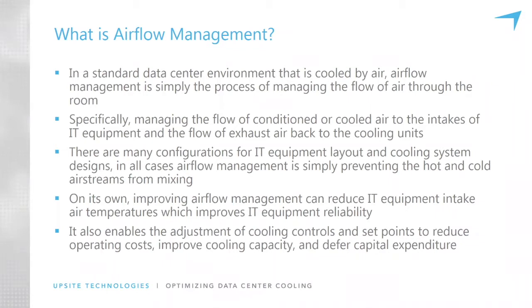It's important to understand that airflow management is not going to reduce operating costs. We'll talk about this more as we continue. But improving airflow management creates an opportunity to adjust the cooling controls and the set points to reduce the operating cost, improve the cooling capacity, defer capital expenditure, and all the other benefits that fall out of that.